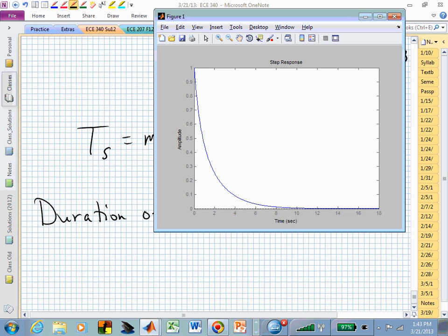So this seems to say, oh, our transient's 10 seconds long, and that's consistent with the step response, isn't it? But what did we say we're shaking it with? An input waveform that was sinusoidal. So this one's not going to die, is it? The transients will disappear after 10 seconds, but after that we'll hit sinusoidal steady state.